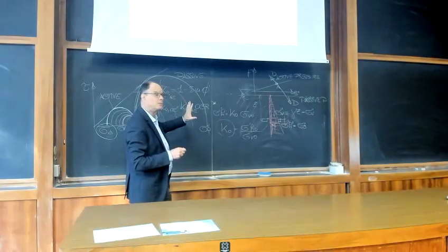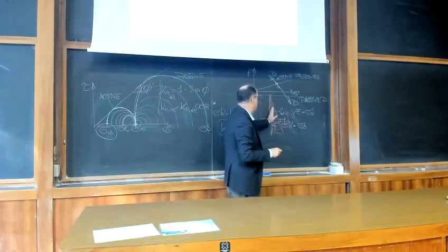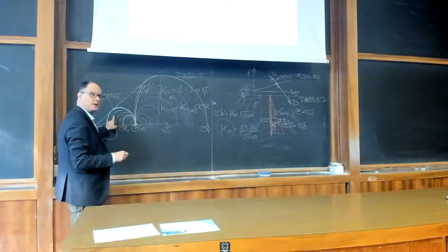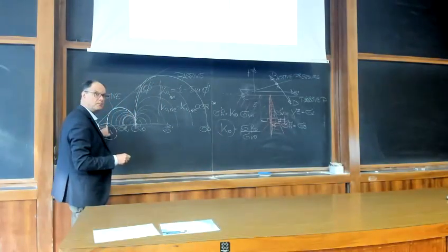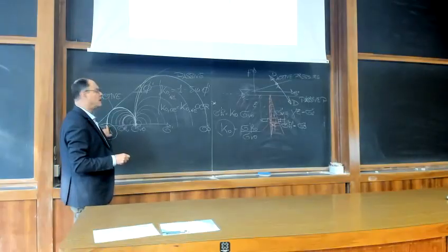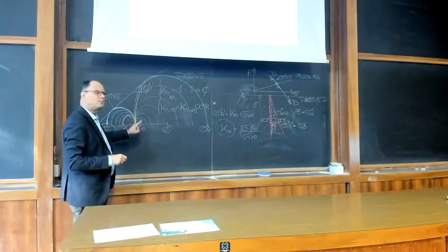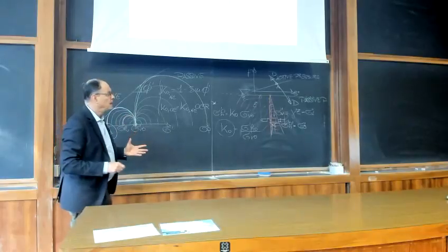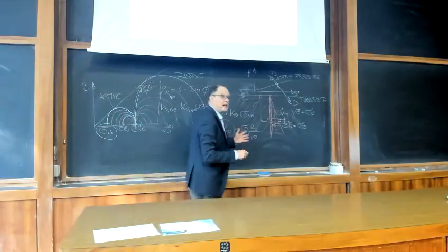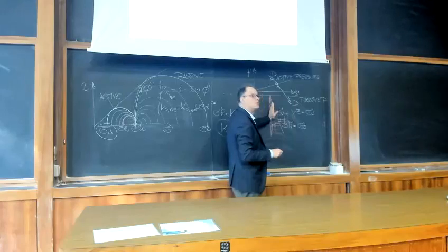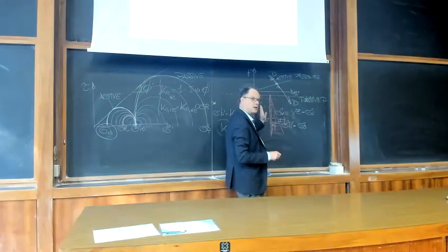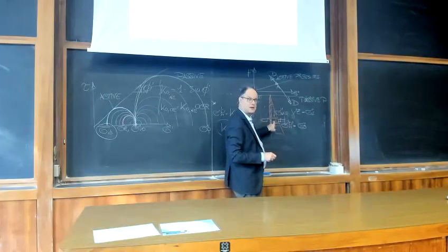This is the maximum. Once this wall starts moving laterally, expanding the soil, the horizontal stress will tend to reduce until it gets to the minimum. So you say, well, okay, my maximum is the initial stress state, and I will use that. And in fact, if the wall is prevented from moving laterally, you have to consider the at-rest lateral stress.